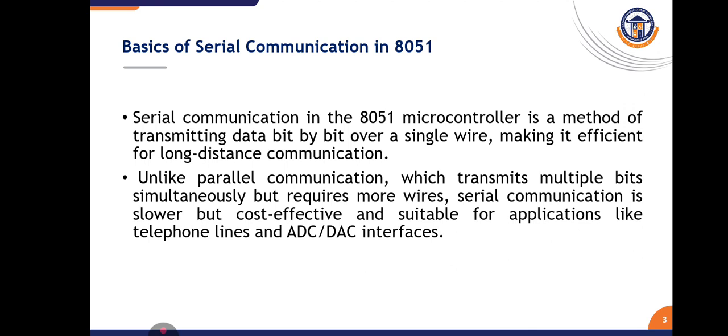Therefore, for long distance communication, the communication outside the microcontroller, serial communication is the preferred choice. Serial communication is the process of sending data one bit at a time over a single communication channel. This method reduces the number of required connections and lowers the cost and complexity of circuits.